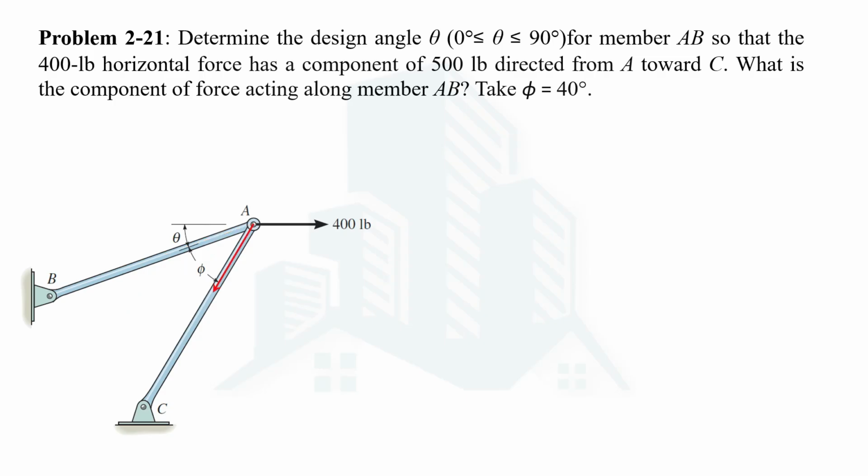So the other way around, if we have the direction of force component in the member AB as from B to A, like the one which you can see here, now let's form a triangle. Let's move the AB force slightly upward. We are not changing its direction, but we are displacing the force along its line of action, which we can do according to the law of transmissibility. And now we are going to displace the force along AC by putting the tail of the AC force at the head of the AB force. By doing so, we can see that we formed a triangle.